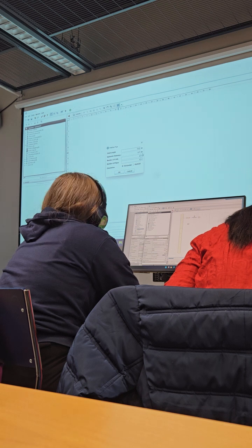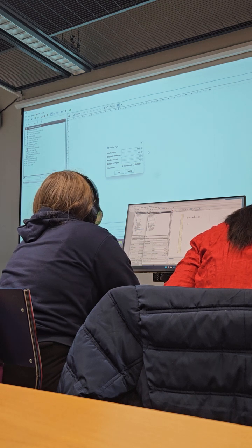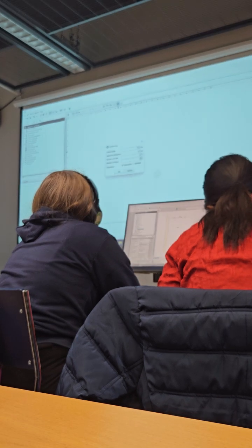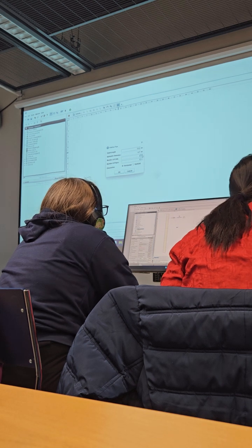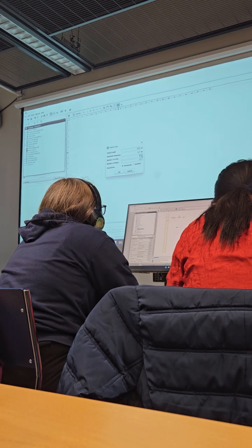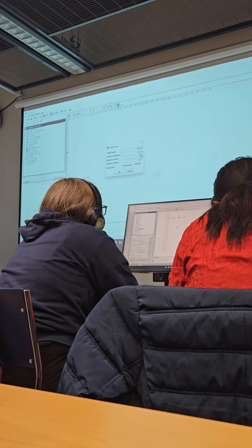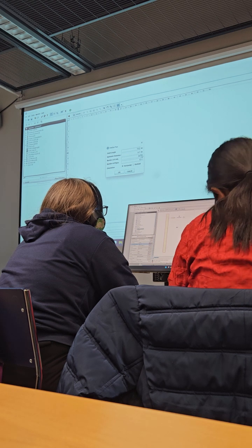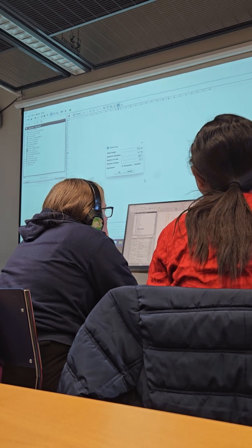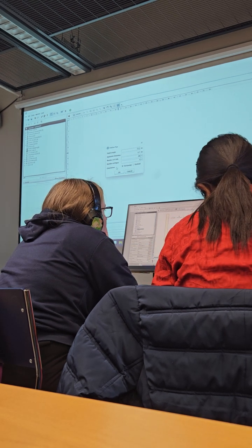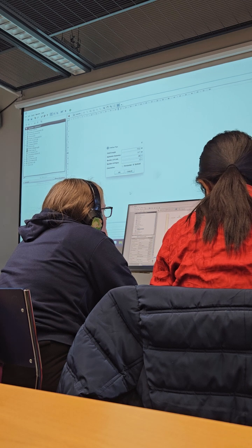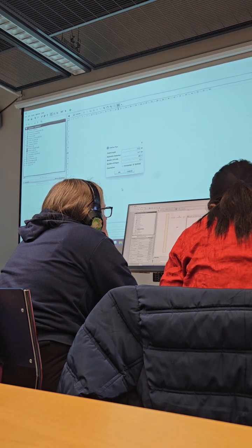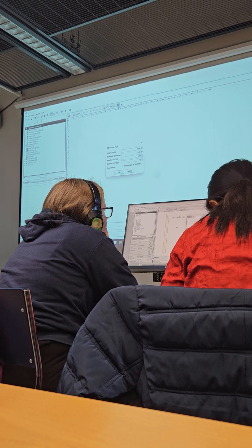Hydraulic diameter I put here now, but I guess it was something like 70 centimeters. And then the number of cells could be, because it's 11 meters high, something like 20 cells, and the orientation is vertical. So these are the basic things for the vertical pipe.